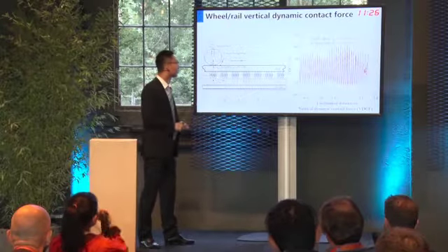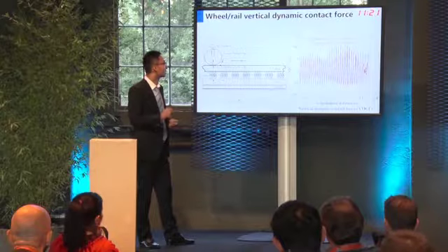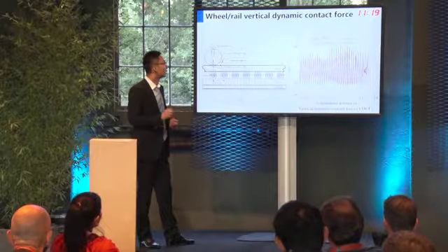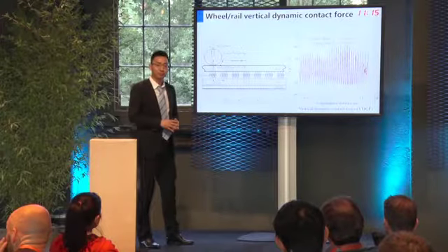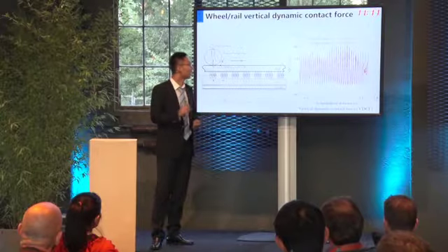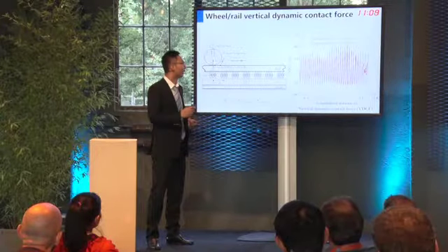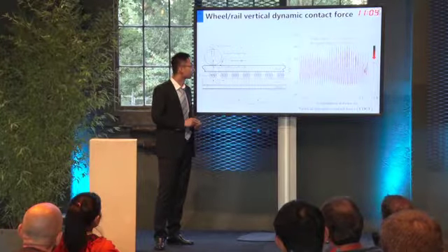The latter figure shows the dynamic force under the corrugation with the wavelength of 31 millimeter and 200 micron depth. It is seen that the resilient wheel can effectively reduce the dynamic force, and the max reduction is about 22%.